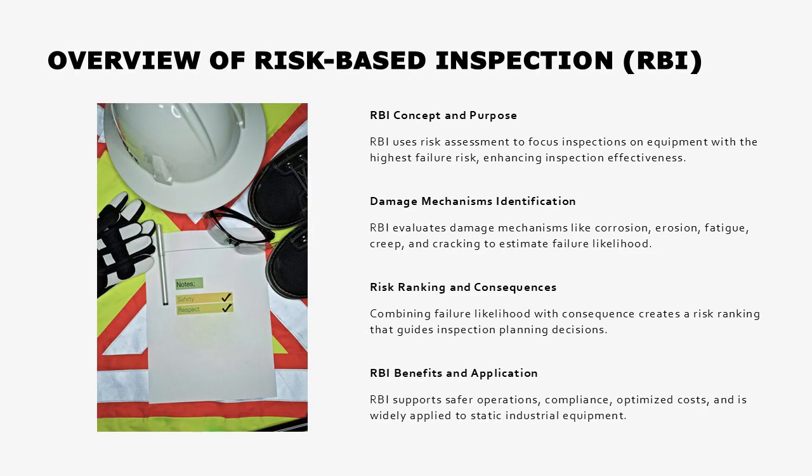Risk-based inspection is a systematic and structured approach used to develop inspection plans based on the risk associated with equipment failure. According to API RP 580, RBI integrates knowledge of materials, damage mechanisms, inspection techniques, and process conditions to assess where inspection resources will have the greatest impact on reducing overall risk. RBI does not eliminate the need for inspection; rather, it improves the effectiveness of inspection by focusing attention on equipment with higher risk profiles.